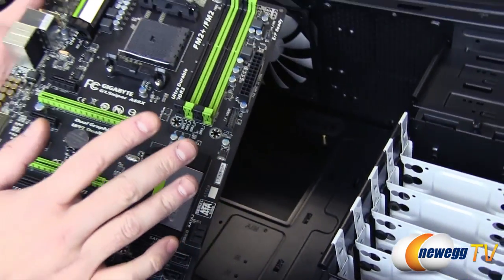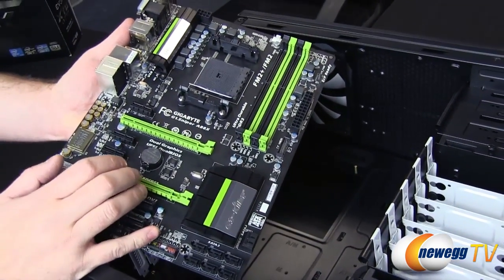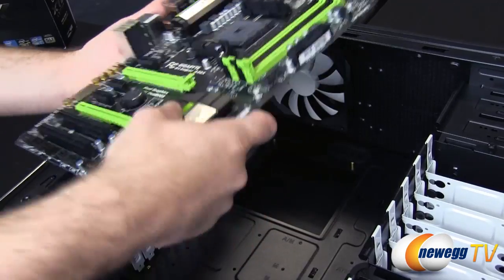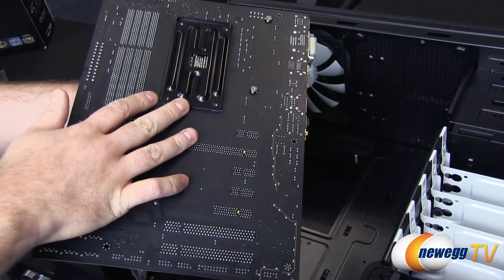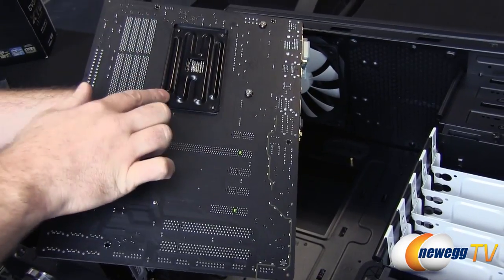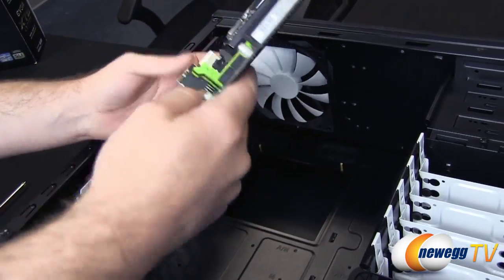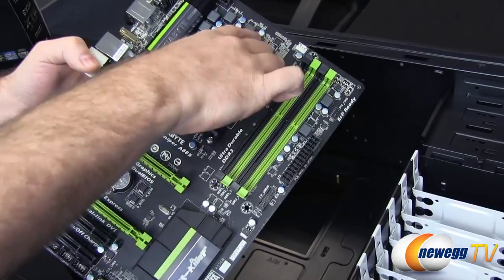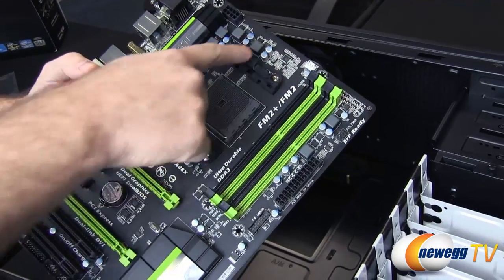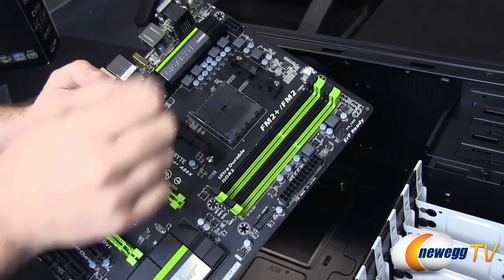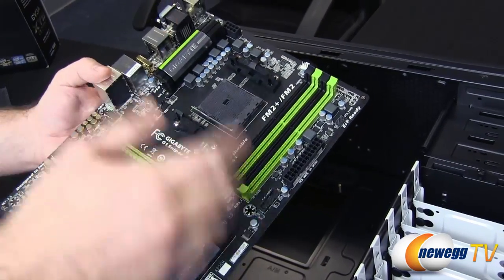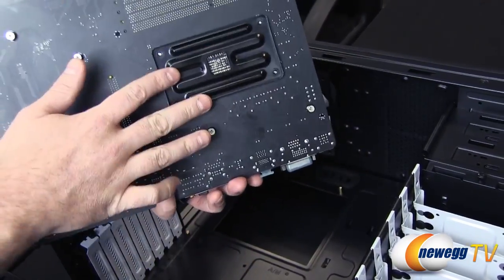But 2 things to bear in mind before you do your motherboard installation, and one is the CPU cooler. This is an AMD CPU, so it's got a universal backplate that's already mounted on there, and a lot of coolers can actually use the integrated mounting points right here. Some of them will have you take off these top pieces and install something else. Others will have you replace the entire backplate as well.